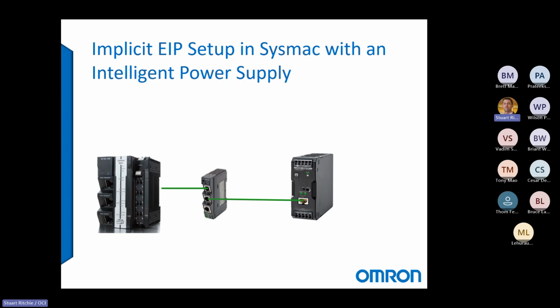And our PLC will maintain that communication link with that device. It will constantly update that data. And if we were to ever lose connection with that device, there are system bits that we can look at that will indicate a connection failure. And if that connection's ever restored, it's self-healing, and that data will resume once the connection's restored.